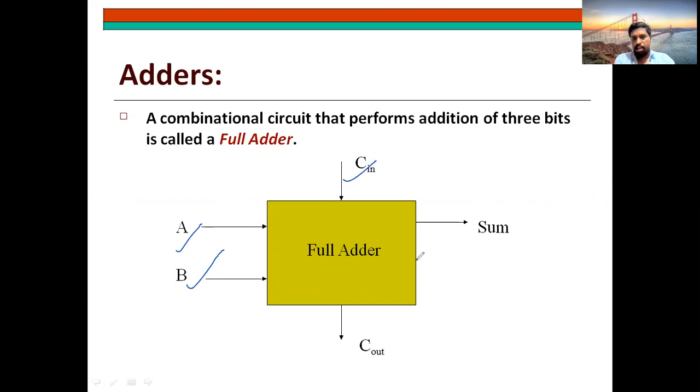And what are the outputs? Generally you will have one as sum and one as carry. You can call the output carry, and you can write it here or here, no problem. That's your wish, there is no rule. You can write it as C out. What is output carry? The final carry which we get at the end of the result is called the output carry. This is the block diagram. These three are your inputs A, B, and C in. Sum and C out are your outputs.